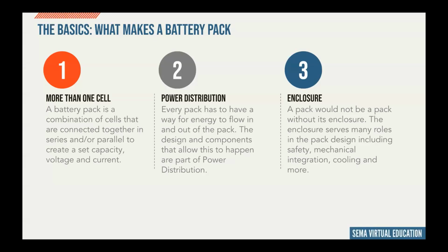The third thing that would define a pack is its enclosure. Enclosures, which we'll get into towards the end, serve many, many different functions. There are some of the basic ones of protecting the internal components from damage from the outside elements, as well as protecting the vehicle and the users from the internals, which is the high voltage and the high current. But from my perspective, these are the three fundamental core elements of a battery pack system.